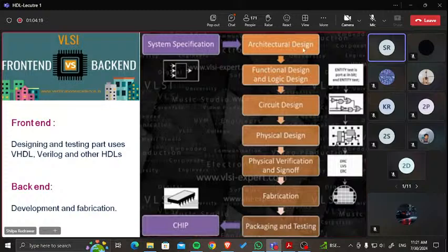So that is called a synthesizable statement and non synthesizable. सिंथेसाइजेबल मीन्स जिसका कुछ हार्डवेयर जनरेट होता है ना. And non synthesizable means which is not having any hardware. Delay. What is the meaning of delay? Is there any hardware required? It has to just wait, so there will not be hardware. So this is non synthesizable. Are you getting?